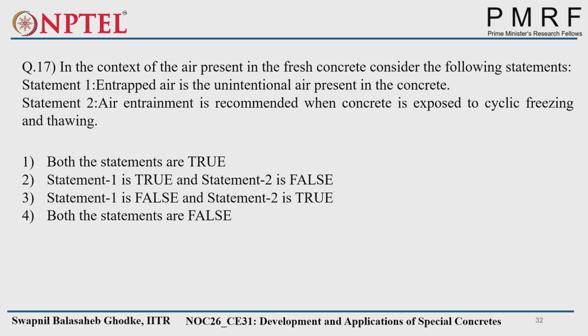Okay. So the next question is in the context of the air present in fresh concrete. First, entrapped air is the unintentional air present in the concrete, and second, air entrainment is recommended when concrete is exposed to cyclic freezing and thawing. Both are true. Okay. Anyone? So all agree both are true then, right?